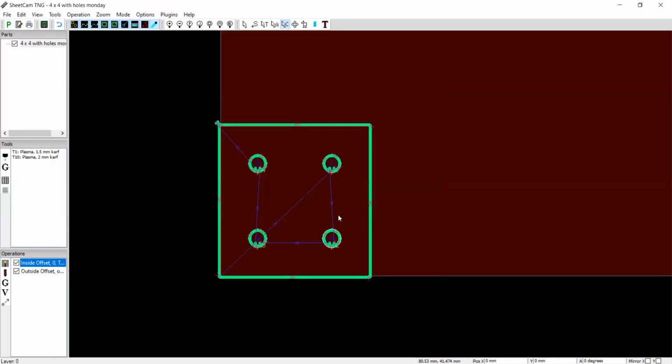This is the standard procedure everyone uses. The change of the curve, stopping the machine and changing it, usually you don't need. But in the start, you have to figure out the optimum values of the curve, of the tip diameters, of the current amperes of the plasma cutter to get your desired results. Once you get it, then it's a simple recurring procedure. Okay, thank you.